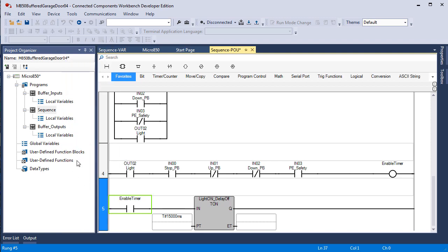If I close this up or I open up this window so I can see everything, I don't have the wraparound and I don't have logic shifting off of the screen. And we could actually close it up more than that, but I just wanted to show you typically what I do if rungs get too wide. I may take sections of them and collectively have them turn on another bit that represents their collective state, and then use that in the actual rung.